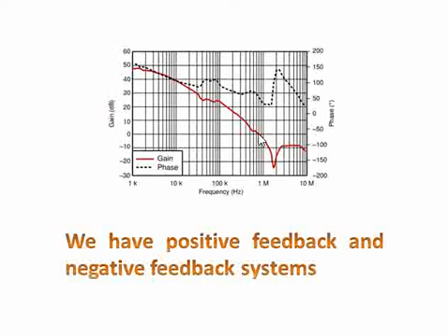As I show with the mouse cursor, this is the point. You can see here that it is 0. This is the point where the phase margin should be very good, such that you have a stable system. That's the actual criteria.